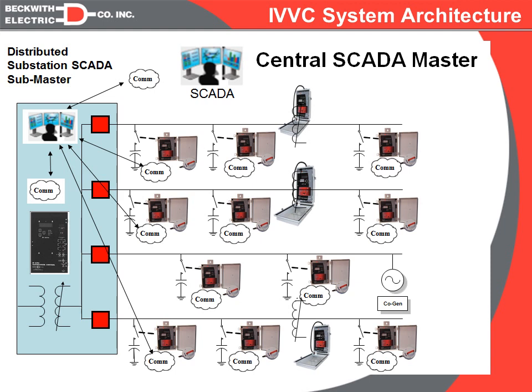So in this case we would have two options. Option one is we could program some logic into this device that says if we lose communications here, we need to stop communicating here so that each of these can come out and go into local automatic mode. The other method would be to select the second option for a heartbeat, which is the direct heartbeat.